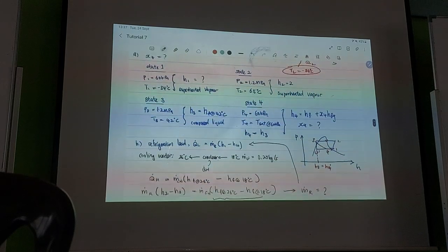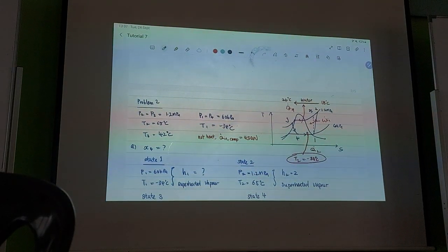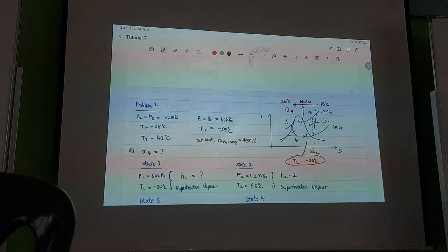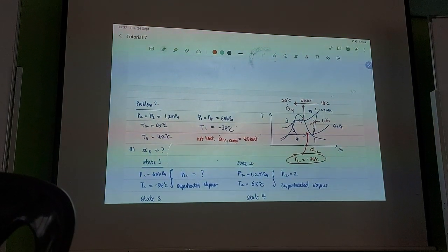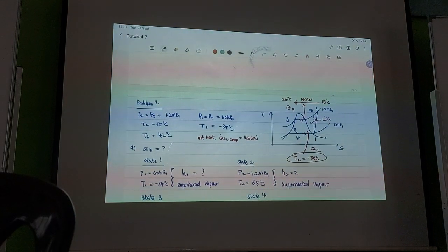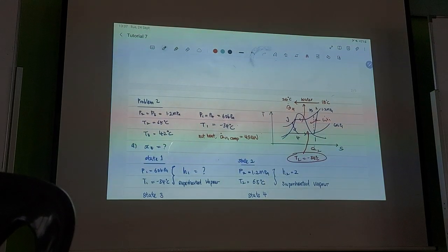So same thing here. Like I said, I think he knew why, but he could not put that into words. So same thing: 18 is the original temperature of the water, and 26 is after it has absorbed the heat. So the water that you supply will always be at 18. So that 18 is your TH, because that is the temperature that you are rejecting heat to.